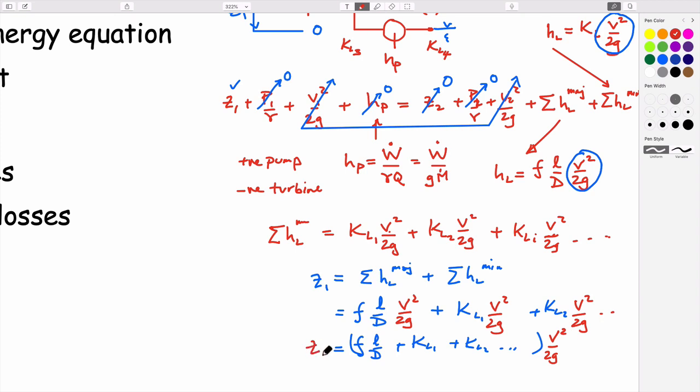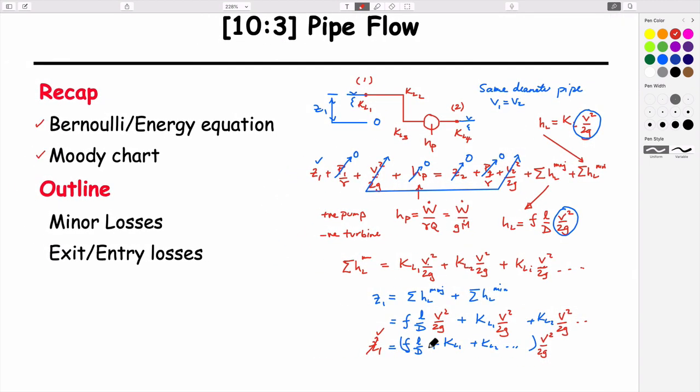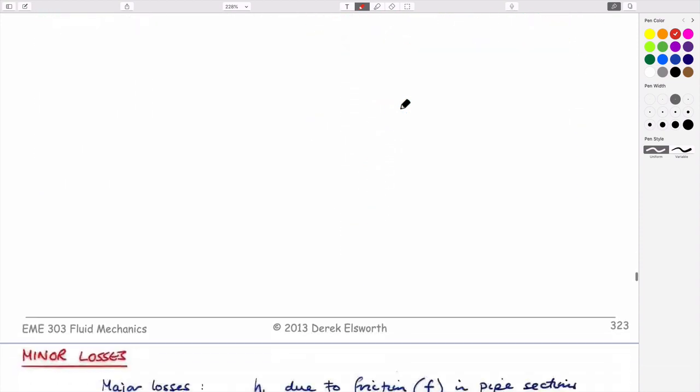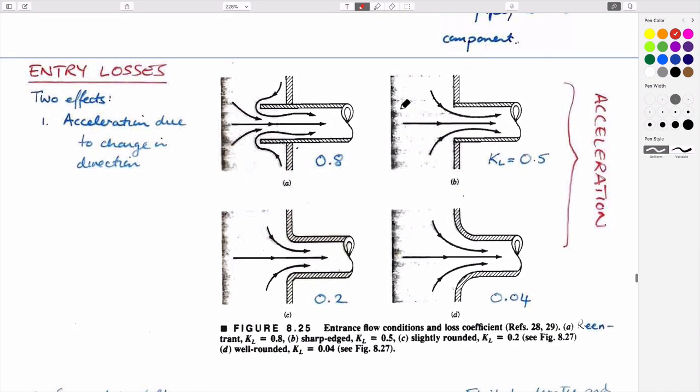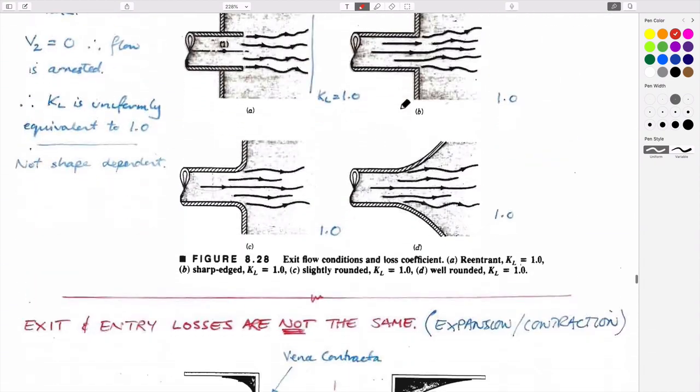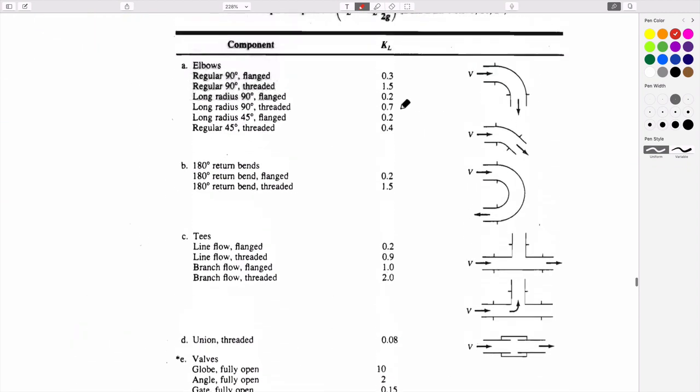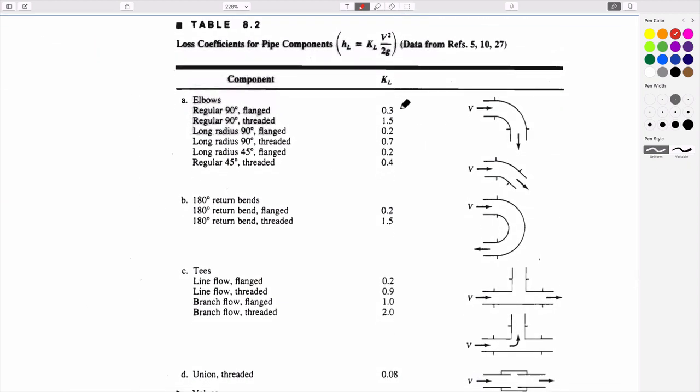And so the only term that we don't know in this is going to be this. And so long as we can define these individual components, then we're able to solve for flows in systems of pipes, with various degrees of complexity, that have these individual fittings in them. So we'll talk a little bit later today maybe about what these losses might be, but I think the only thing to realize is that they exist and can be quantified in terms of tables that say something about what those losses should be.